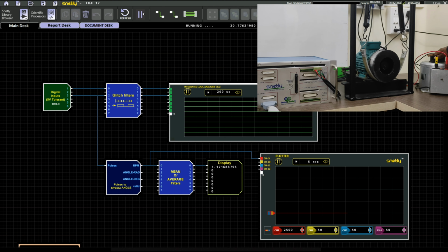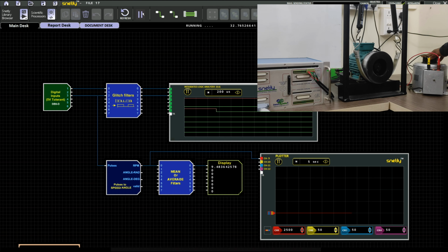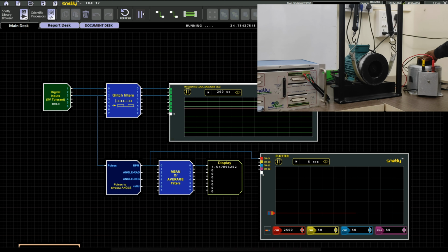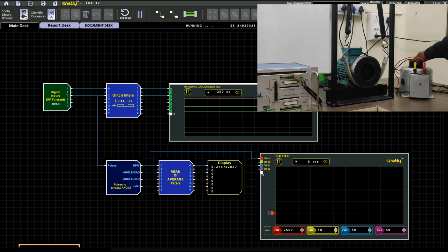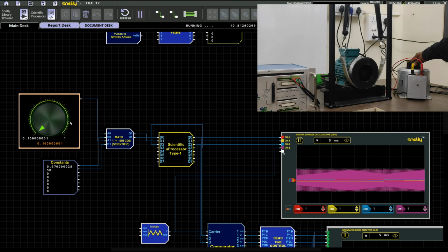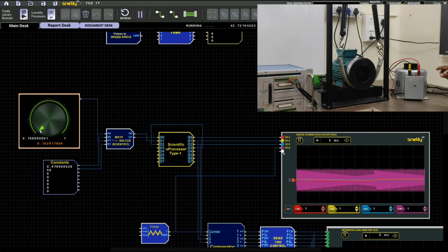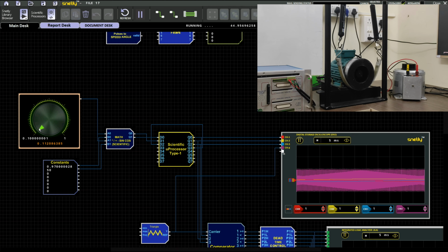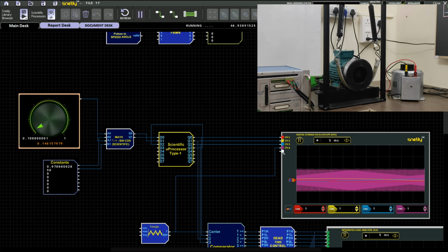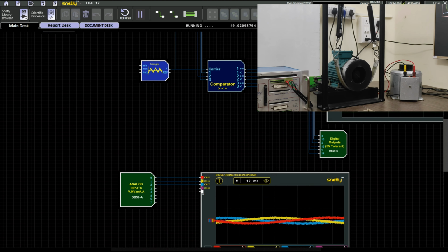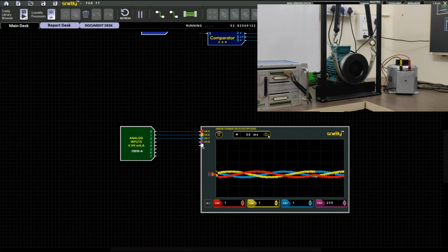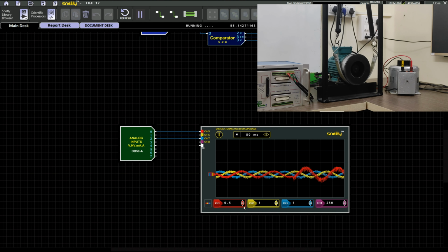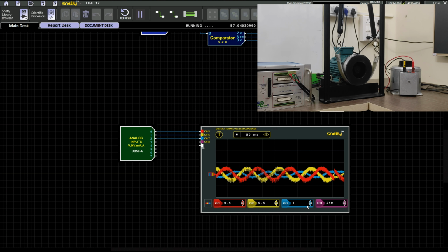By simply varying the knob, we will get the variation in amplitude as well as frequency of your reference signal, so that the modulation index of sine PWM will be changed. Based on that we will get a respective voltage around the voltage source inverter module. Then the motor starts to rotate. Once the motor starts to rotate, you can observe the current waveform in the analog signal area.